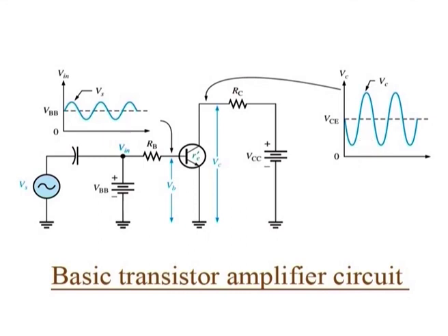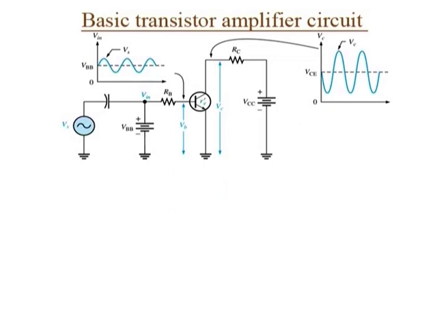The forward biased base emitter junction presents a very low resistance to the AC signal. This internal AC emitter resistance is designated r'e in the figure and appears in series with Rb. The AC base voltage Vb is equal to Ie r'e.